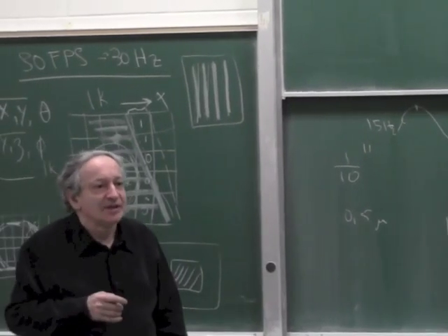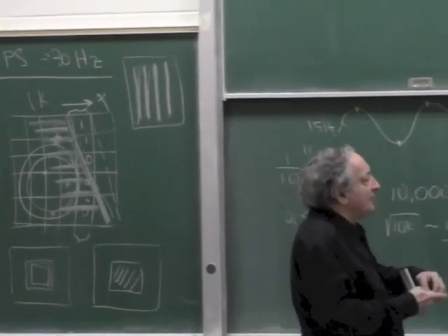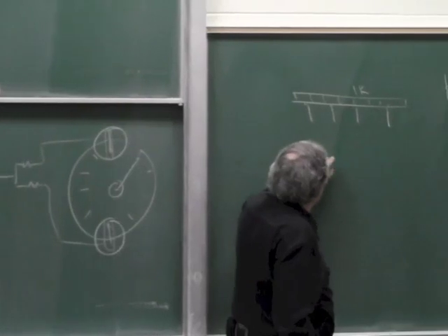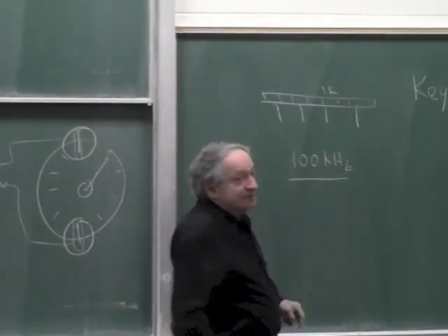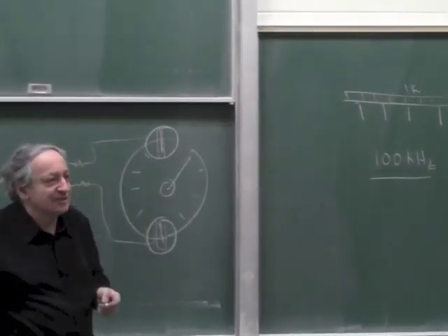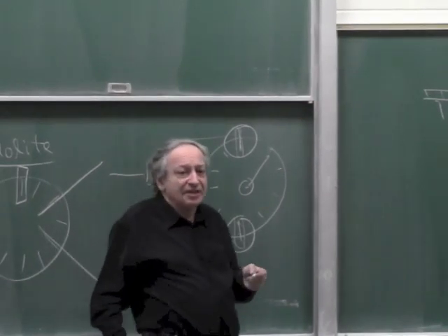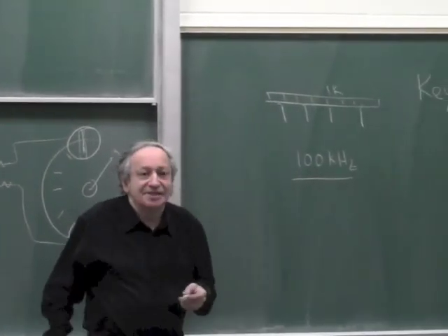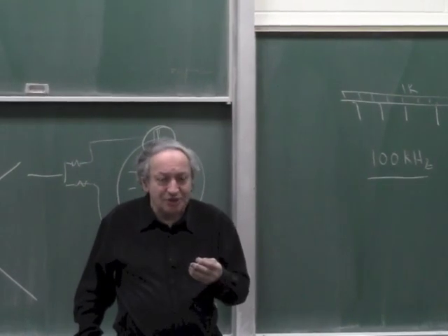So what is the fastest you can get as a camera? Okay, so I'm not sure I'm up to date, but linear cameras you can certainly get with a 100 kilohertz rate, because I've used them at this rate, so I know you can, even years ago. And I can do a quick estimate because you can make a simple, fully parallel array as a custom chip.